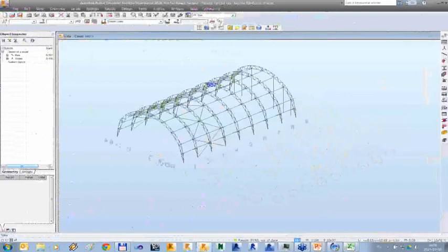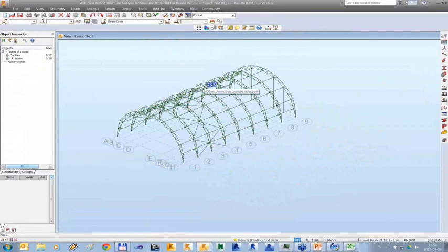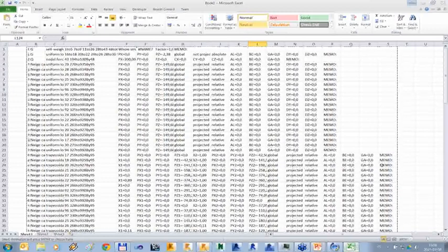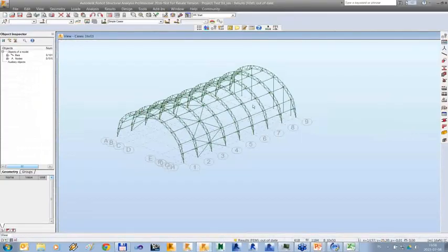I think that what you have to do is, when you look at the load table, there are numbers, and then there is a separate column for load case name. So you make sure that in Excel the first column is like that, so two columns. But it is possible. Of course, the number of load cases should be created prior to copying from Excel. Exactly.